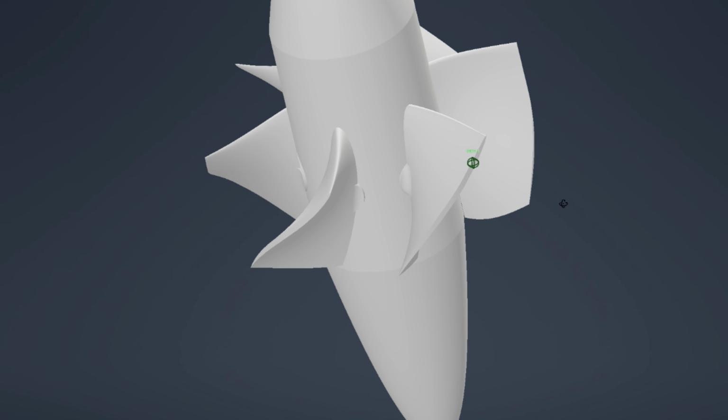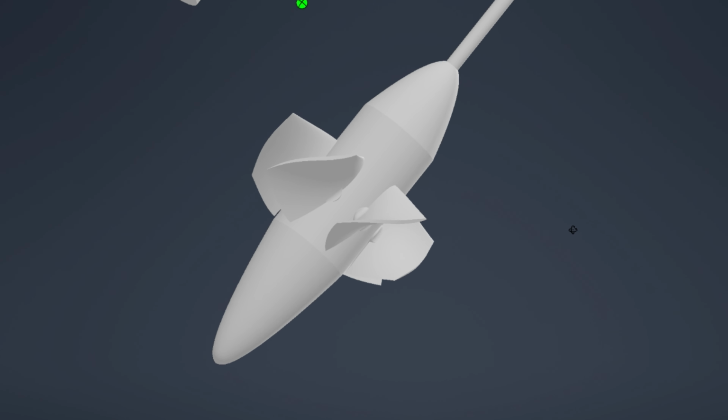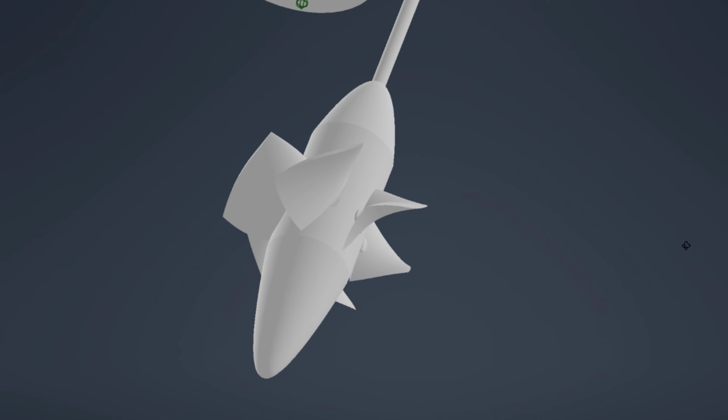The draft tube. Only one piece left, and on a low head machine, maybe the most important one of all, the draft tube. Everything downstream of the blades. Think about the water the instant it leaves the runner. We've stripped out the swirl, dropped the pressure, but it's still moving and heading straight down the axis. All of that speed is energy we haven't captured. Dump it back and you throw it away. And on a 4.8 meter machine, that leftover kinetic energy is a big slice of everything we've got.